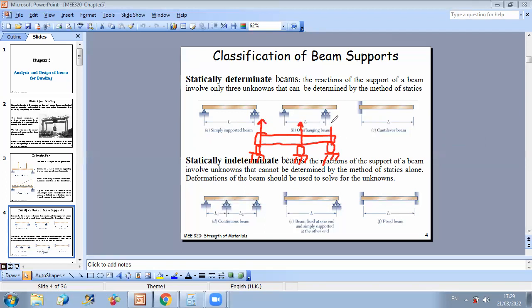So in case you have an axial load, first, you cannot sustain it, no equilibrium. Plus, if you have a transverse load and you want to solve for your 3 unknowns, you will not be able to. If you write 3 equations, 2 of them will be redundant. They will be proportional to each other. So you cannot solve, because here the third equation, which is sum of x equals 0, will not give you anything. Whenever you just apply transverse load, you don't have axial forces. So already sum of x equals 0 is not used.